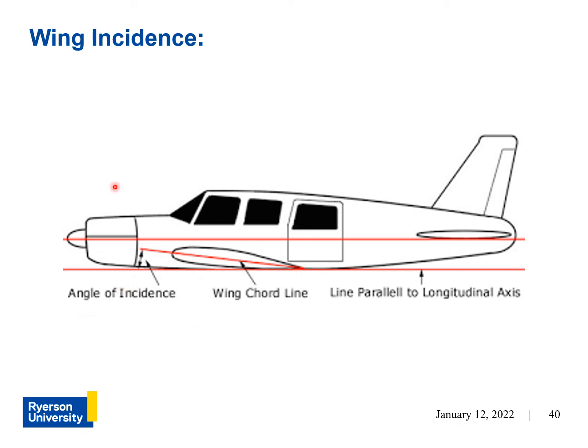Now, wing incidence angle is chosen to minimize the drag from the fuse at some flight condition. So the wing incidence angle is just the ideal angle at which the wing is with respect to the fuse, so that the fuse produces either less drag or actually, in some cases, even produces lift in addition to the wing.